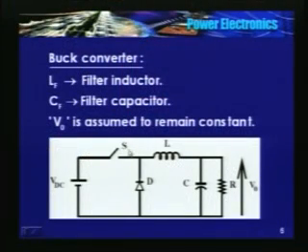So the S here is a self-commutating switch. If the power level is low, you use a MOSFET. Invariably if someone says SMPS, the first thing that comes to my mind is a MOS. It could be a very safe assumption. It could be a MOS, and it is a very fast device.